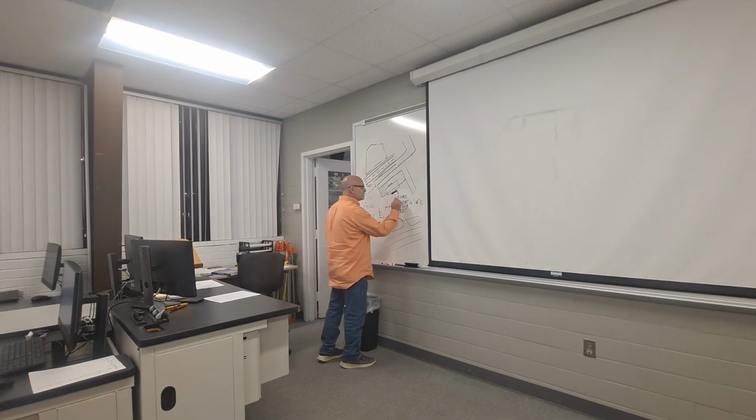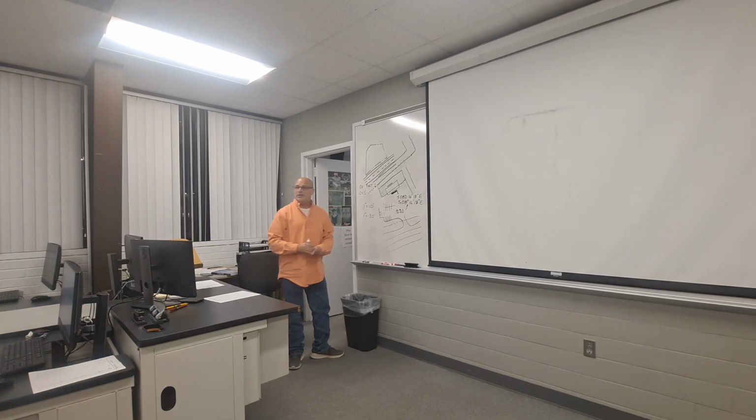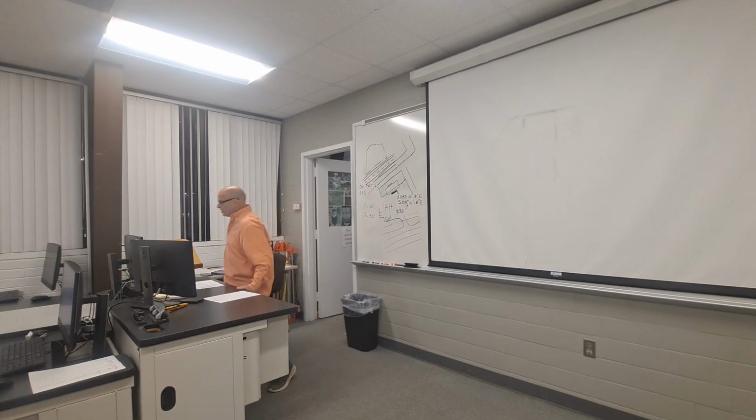To type it in, it's S08D, 16, and then your foot mark, which is the minutes, 18, and then an inch mark, and then E. And like I said, I'm going to draw some of these for you in a minute. However you write it down in your notes, that's how it would be written out normally. So that one was south 8 degrees, 16 minutes, 18 seconds east.